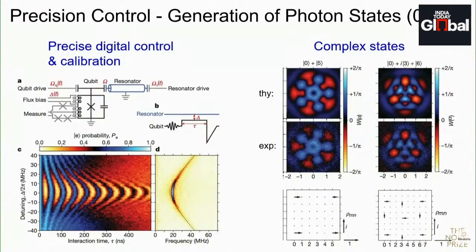We were making qubits at that point, and we connected a qubit to these resonator circuits. And what we did in this particular circuit is we can calibrate up the qubit. On the bottom left curve, we can put the qubit off resonant, so it's not talking to the resonator, or on resonant, having it talk, calibrate that up so that we can controllably transfer photons from the qubit to the resonator.